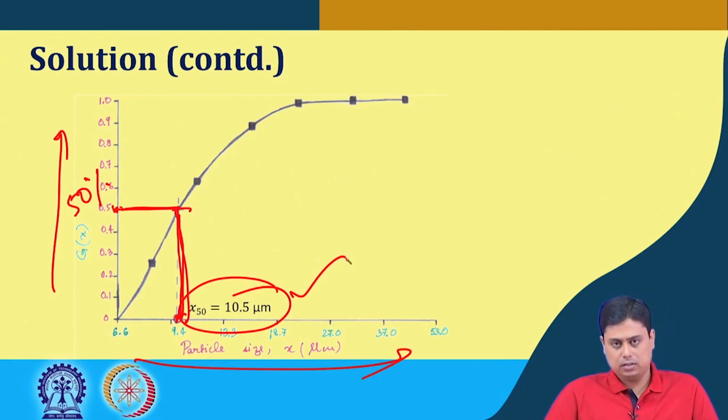I hope this is clear to you, that if we have the size distribution known of at least 2 of the inlet or outlets, then we can calculate the third one. We can also calculate the grade efficiency from the size range data. From that grade efficiency we can find out the equiprobable size.